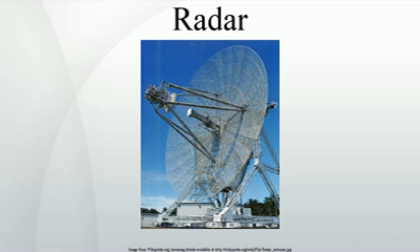Matched filtering allows the entire energy received from a target to be compressed into a single bin, be it a range, Doppler, elevation, or azimuth bin. On the surface it would appear that then within a fixed interval of time one could obtain perfect, error-free, detection. To do this one simply compresses all energy into an infinitesimal time slice. What limits this approach in the real world is that, while time is arbitrarily divisible, current is not.